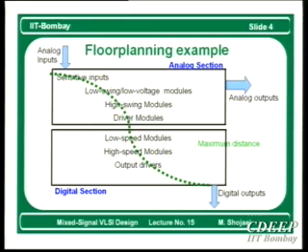Because doping in the substrate is not very high, therefore the effective resistance of the substrate is not low. This is one point. The second point is, the substrate has a lot of parasitic capacitance with all the transistors, right? Even with wells. Therefore, you have a distributed RC. And this distributed RC actually couples many modules in the circuit together. Therefore, you may feel that, okay, everything is well separated, but you have to be careful how they are connected through the bottom of the wafer, which is in fact the substrate. That's why we have to be careful about guard rings and shielding also.